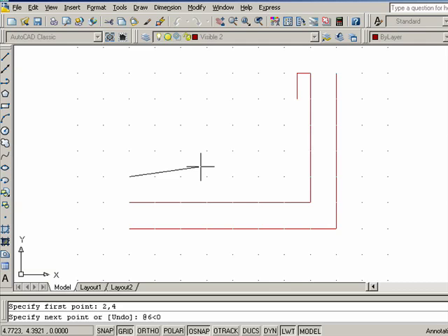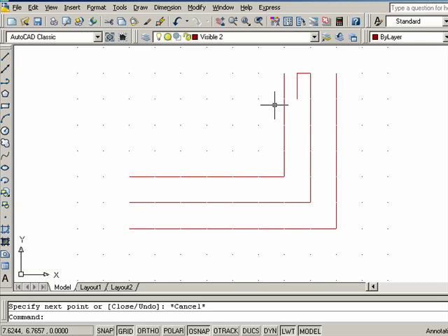Remember that with AutoCAD, 0 is in an easterly direction. Now I'm going to go straight up. I'm going to go 4 inches, less than caret, 90 degrees. I'm going straight up. Escape or enter to finish the command. That was polar coordinates. Line. I'm going to begin this line at 2, 5.